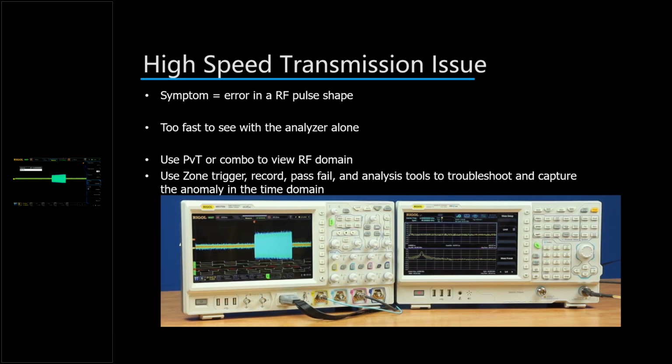If we go back to live mode here, turn record mode off for a second, we can turn on our digital channels. So we're looking at a digital line associated with the board that's driving these signals. And we can start to look at the frequency independently of these different signals.